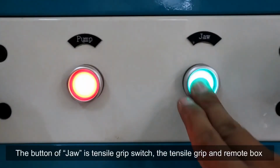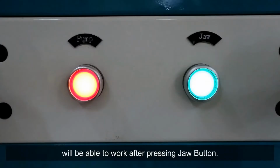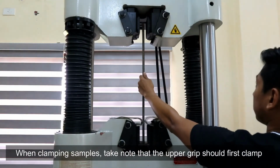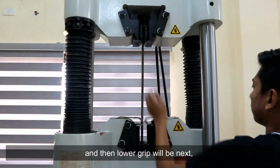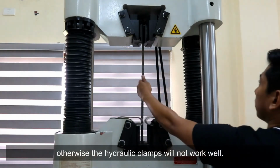The button of the jaw is the tensile grip switch. The tensile grip and remote box will be able to work after pressing the jaw button. When clamping samples, take note that the upper grip should clamp first and then the lower grip next. Otherwise, the hydraulic clamps will not work well.